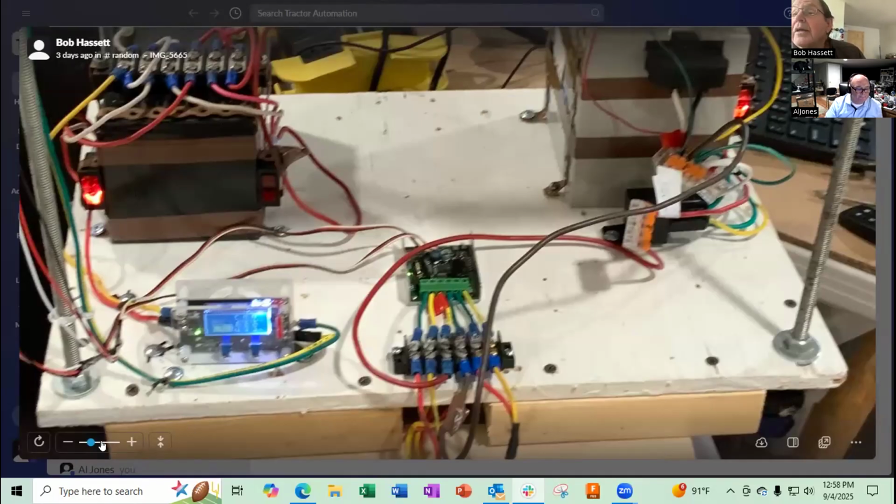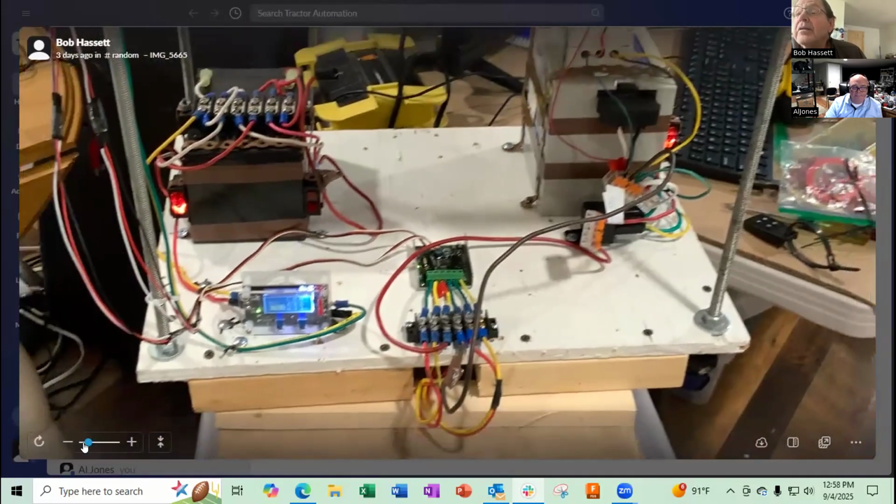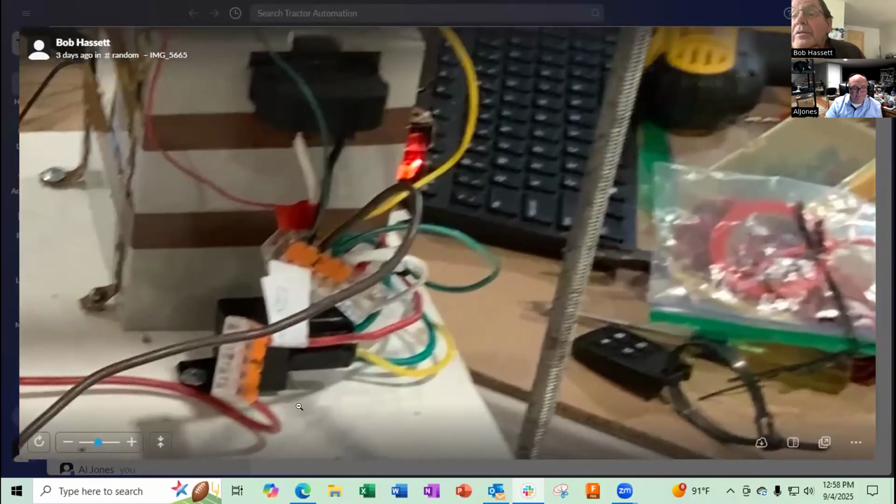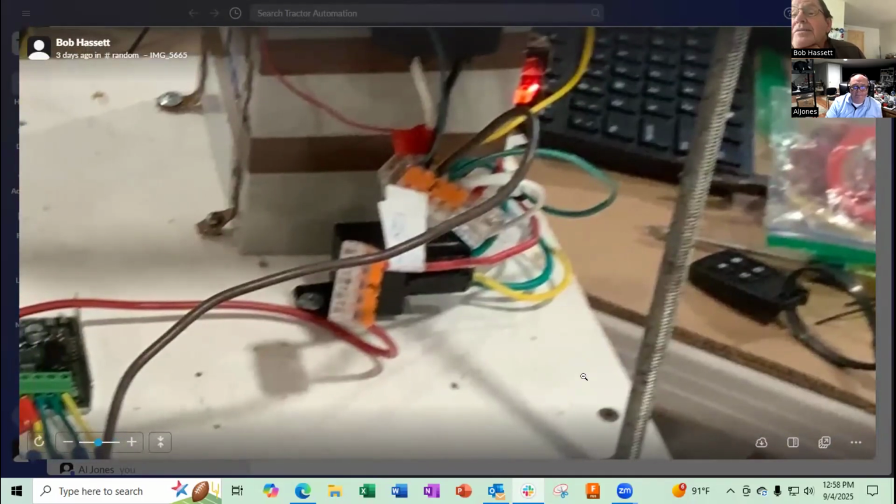Over there on the right, I used electrical connectors, all kind of garbled up. So I want to take that apart and make it a little more organized. I'm going to use one series for positive and one series for negative. That way, terminal strips just kind of get big and bulky with spade connectors. So that seems to be working, but I want to make the wires longer and then secure those connectors so they aren't bouncing around.